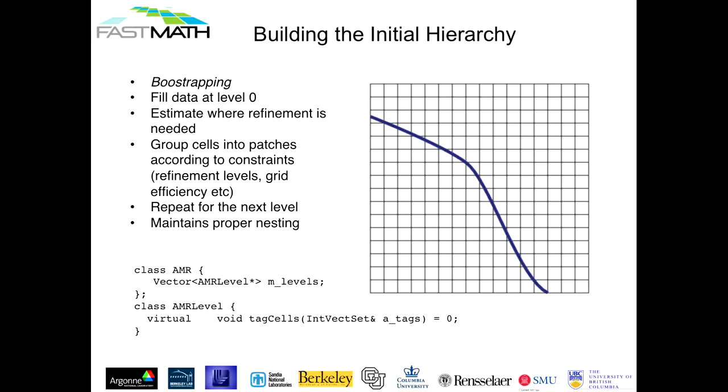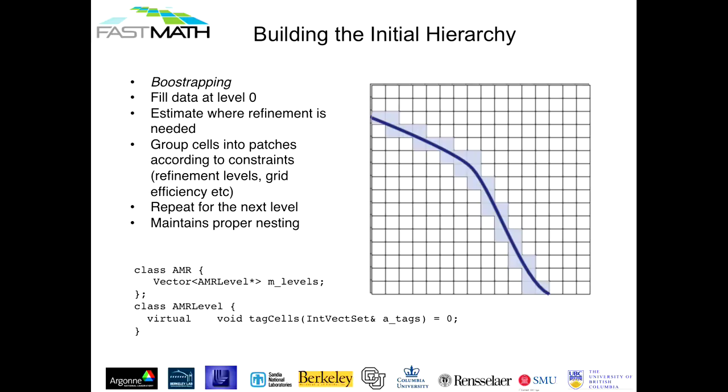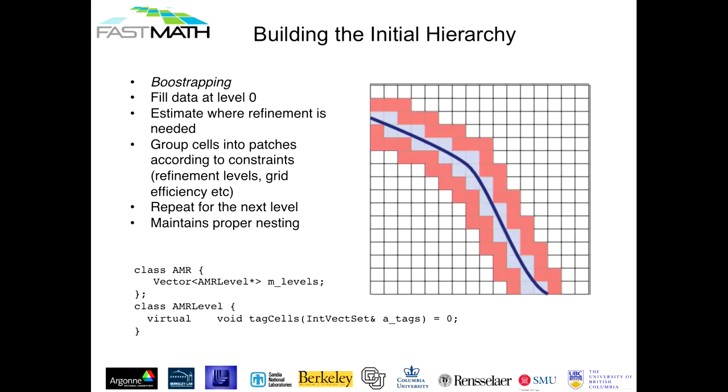So say I have, in the blue region, some very discontinuous property. On the left, maybe I have unshocked gas, and on the right, I have high pressure detonation, or that's an interface where porosity changes dramatically, or it's an interface where some nice uniform grid is not going to get the right answer. So you put tags down, so you mark those cells as needing grid, and then you tag cells, you go to the next level, you go back, and you make new grids,